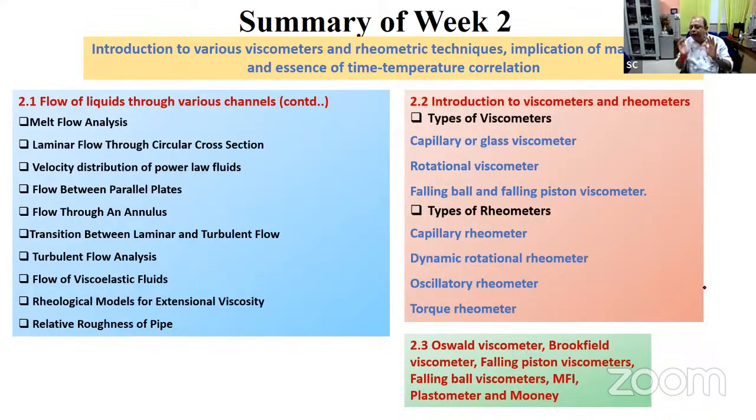So in general, we try to touch upon the general viscometers possible for measuring materials, including rubber, plastic, and fibers, which have high viscosity, as well as paint and adhesive, which are low viscosity. Ostwald viscometer, Brookfield, for example, for adhesives and paints, you can assess pretty well.